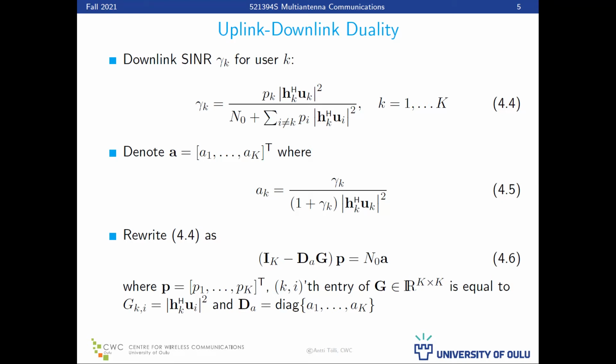Interference and noise are independent, so the cross terms vanish when you take the expectation. Then you have just the variance of the interference plus the variance of noise. We can take the expectation of the interference and of the noise separately, because they are independent. Right, so that's the essence of the SINR.